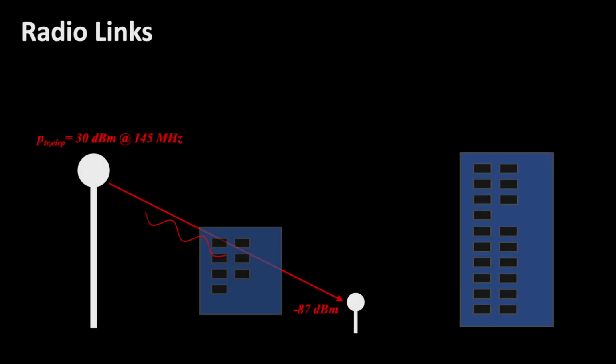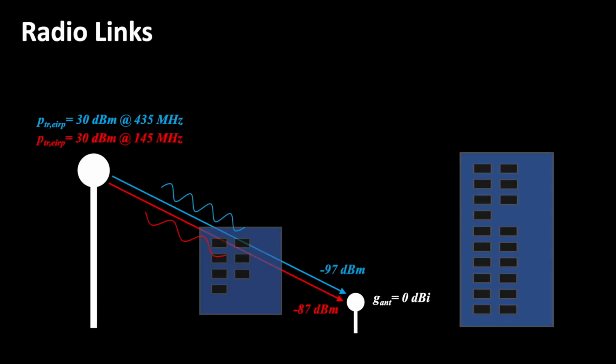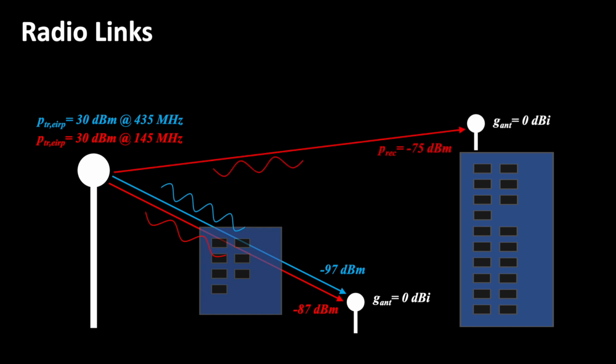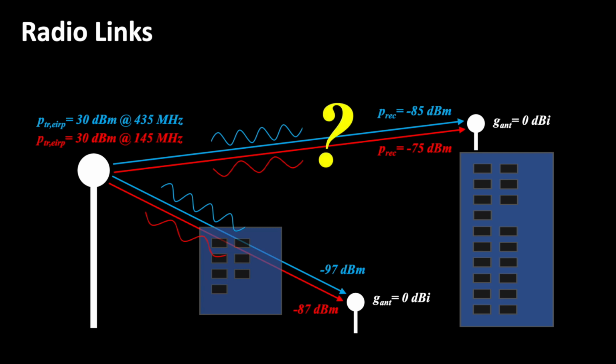Received signals on high frequency are weaker than on low frequency, even when transmission power and antenna gains are the same. We know that short electromagnetic waves suffer more from shadowing and penetration loss. However, there is an additional effect lowering the signal, even on a line-of-sight connection. While explaining, we are deriving useful engineering formulas to calculate received power, power density and field strength.